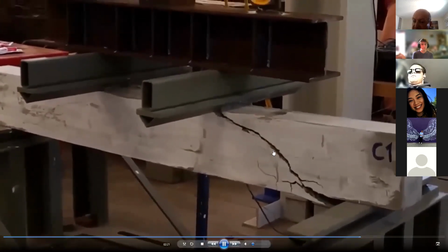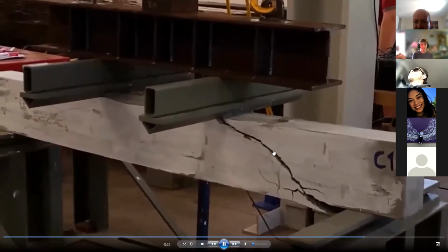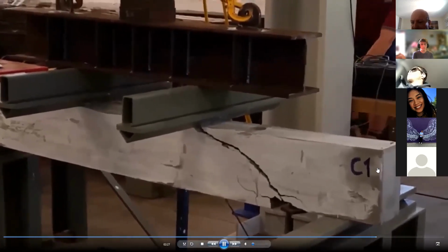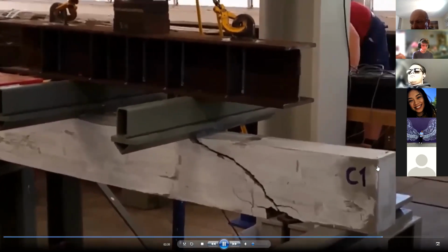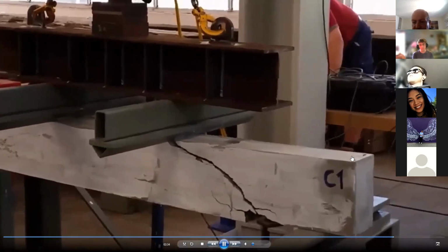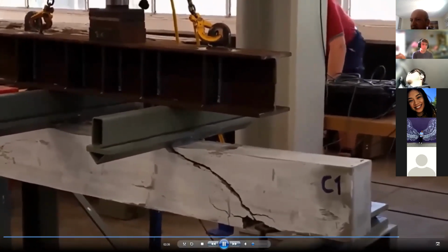The bad thing about shear failure, when it happens to beams, you don't see much deflection. So the beam doesn't deflect, there's no deformation. It's a sudden failure. So all of a sudden the beam is going to be collapsing. And you don't see the crack if you have a ceiling because you don't have lots of sagging.